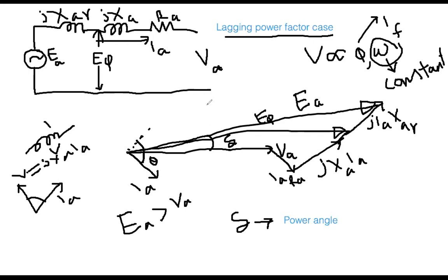This means that because the power factor was too much lagging, you have to generate a much higher voltage here. Otherwise, you cannot provide this voltage there. That is the meaning. Here the consumers are connected and they are consuming power, which is mainly lagging power. Accordingly, that is causing a lagging power factor.